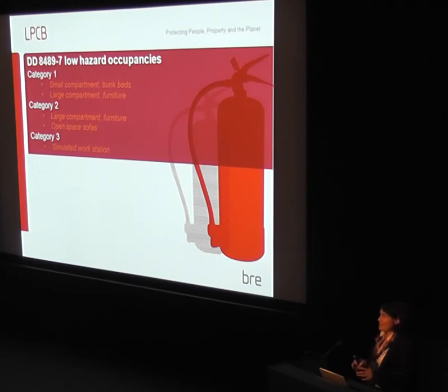And this has been named differently from ordinary hazard 1 because it's felt that with sprinklers you're looking at whole building protection, but with water mist you're often going to be looking at certain compartments within a building that you can protect. And in different areas you actually might need a different design of system. And so it's more of a room space protection arrangement.